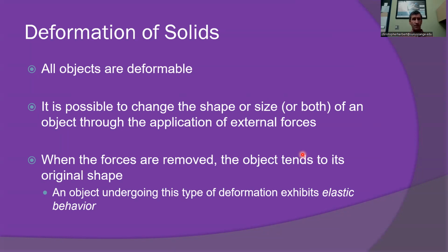Now, at small forces, these bonds pretty much act linearly like a spring and therefore would obey Hooke's law. At larger forces, we begin to have a nonlinear response between the bonds, but eventually the bonds begin to break and the material will fail.